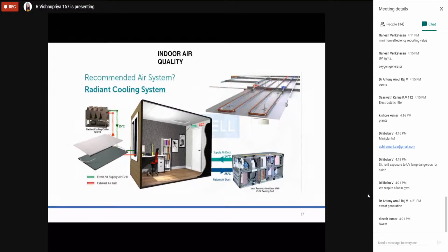Okay, next. But the intention why I am saying this point is, the capacity remains the same. The fan delivering air quantity, the air quantity plays a major role, right? It takes the pollutant to a different area, but I'm avoiding 50% of the air. So I'm avoiding the air carrying the pollutant to a different space. This is one of the good systems for maintaining better IAQ.